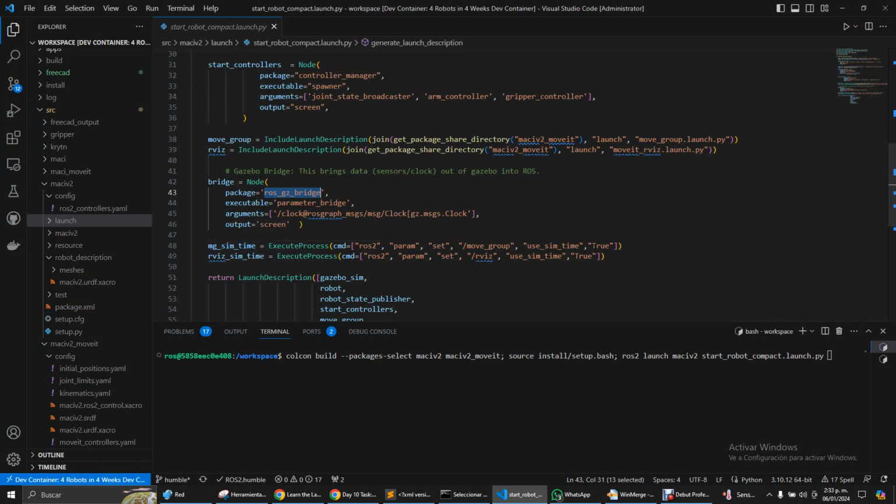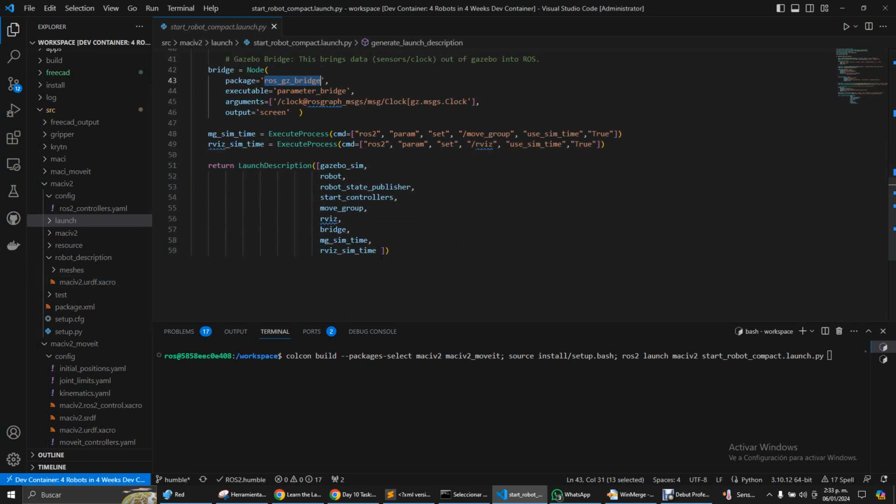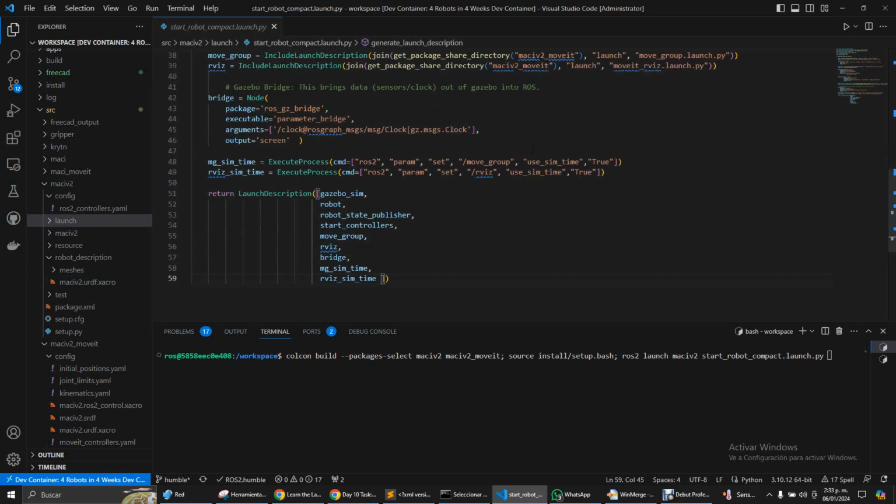Last but not least, this is very important. You have to synchronize the messages and the Gazebo sim time or the ROS sim time, everything together, to follow all the information about the sensor. This is very important because you need to communicate at the same frame time. If not, you will get some kind of messy errors, and you will not know what to do.